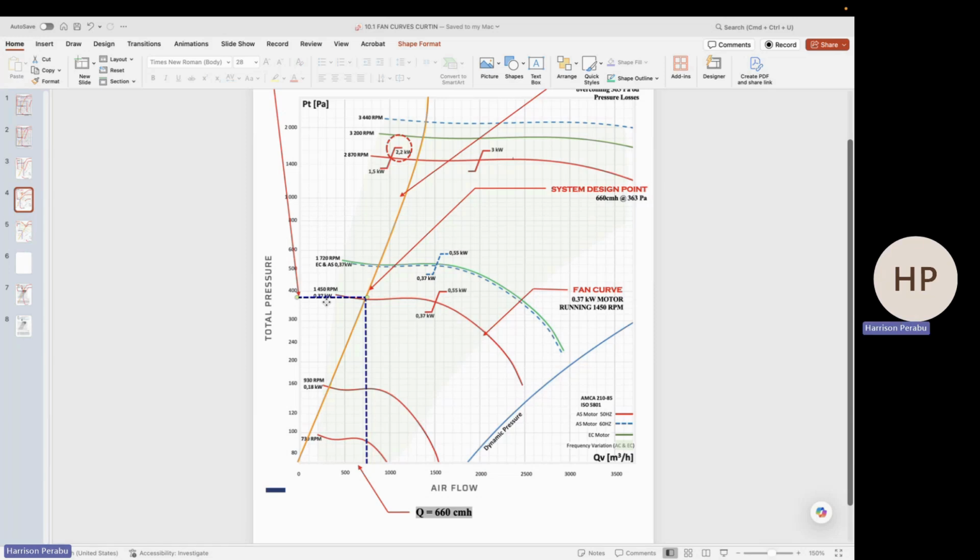Now, the other issue here would be picking a 2.2 kilowatt, class 3 fan which runs at 2870 RPM. You are churning a very high noise, which is obviously going to create a noise risk issue. On top of it, you're running very high amps and unnecessarily wasting it on noise generation, high sound generation. So is it really worth it?